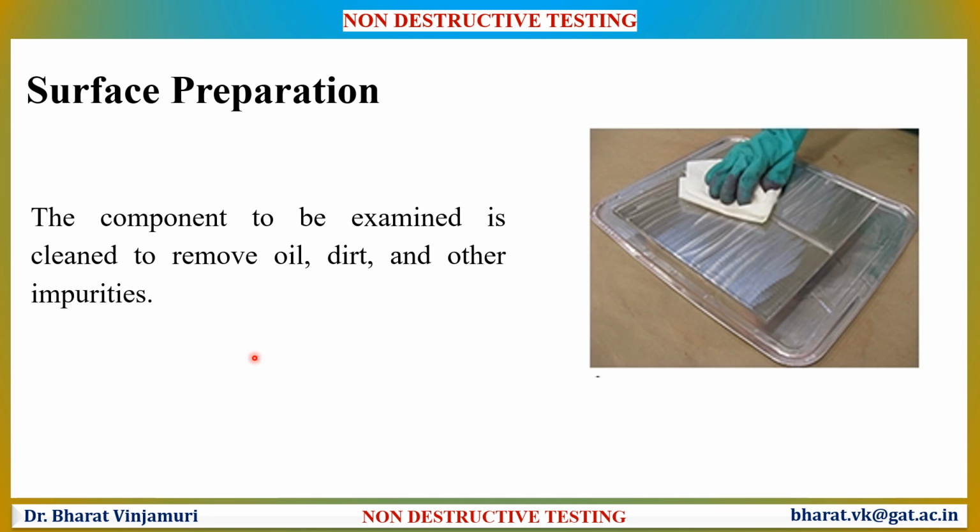Surface preparation is the basic process which has to be carried out during any NDT process, which basically involves cleaning the component which has to be examined thoroughly so that oil, dirt or any other impurities will be removed from the surface.